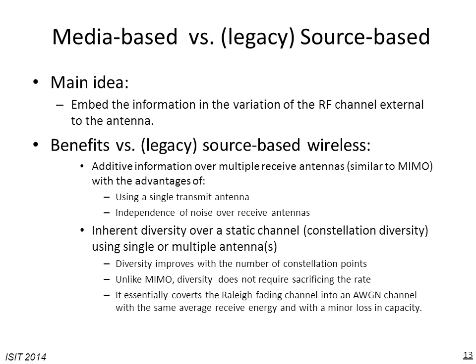And if we compare a 1 by K media-based system, 1 transmit antenna and K receive antennas, we have other benefits with respect to a K by K system. We have indeed 2 other benefits. The first one is that in media-based modulation, the noise over the receive antennas will be independent.